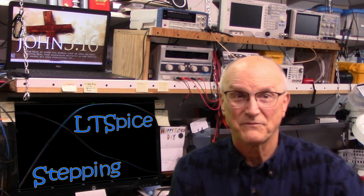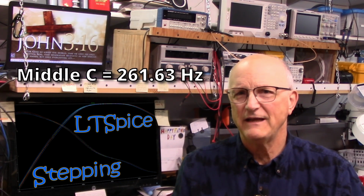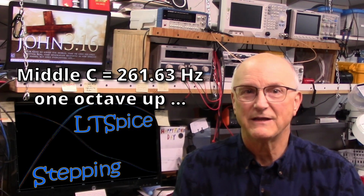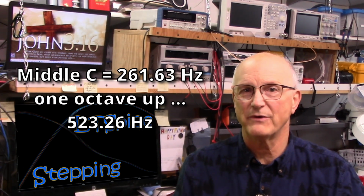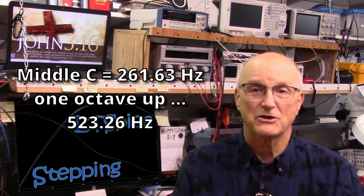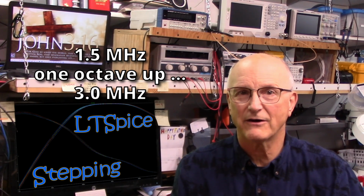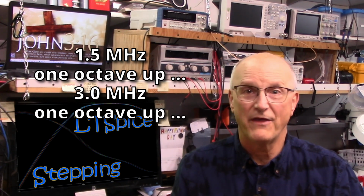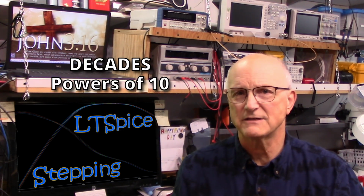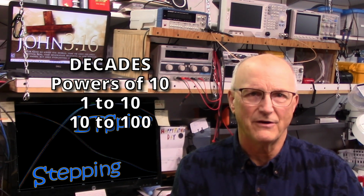That's a good question. An octave is just like in music. The frequency of middle C is 261.63 Hertz. 1 octave up to the next C is 523.26 Hertz, exactly twice the frequency. In terms of electronics, 1 octave up from 1.5 megahertz is 3 megahertz, and 1 octave up from that is 6 megahertz. Decades, well, that speaks of powers of 10. So from 1 to 10 is 1 decade. From 10 to 100 is another, and so on.